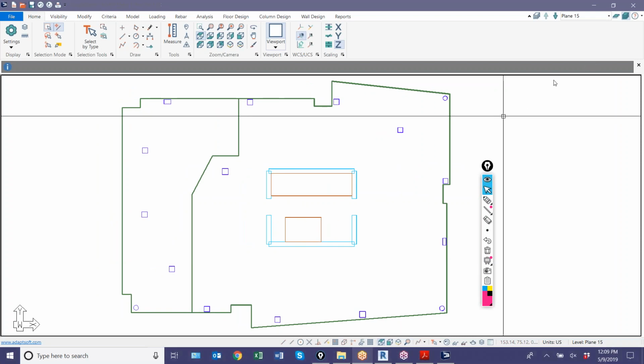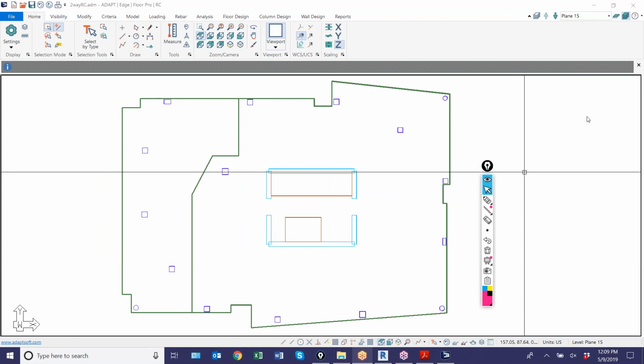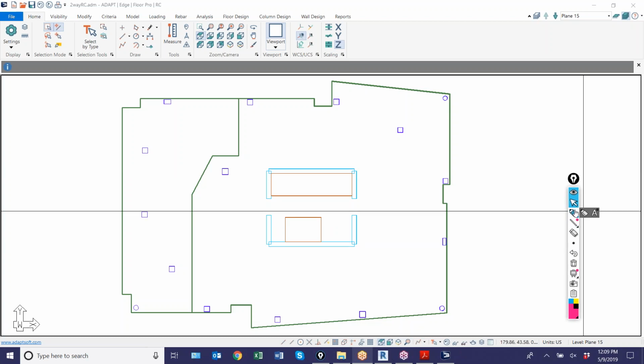Once we enter the modeling space here, you can see that we automatically go into a plan view in what we call multi-story mode. So multi-story mode is this nice button here. The one next to it is single level mode. Single level versus multi-level.